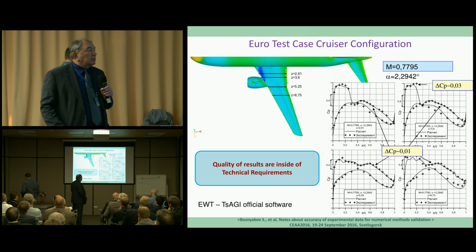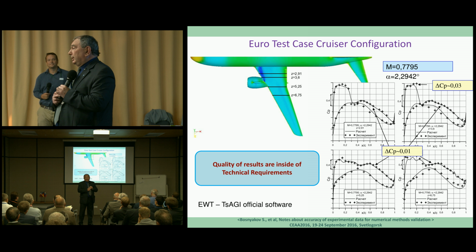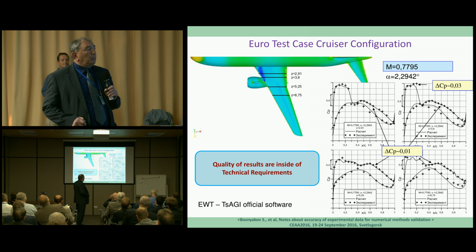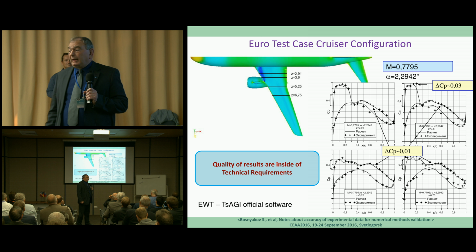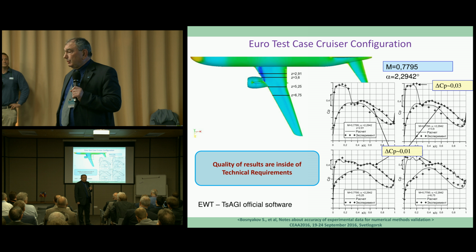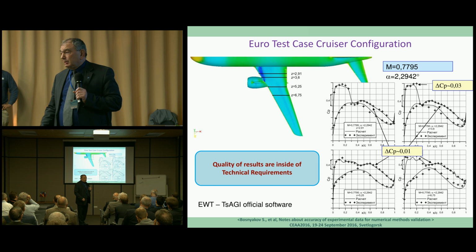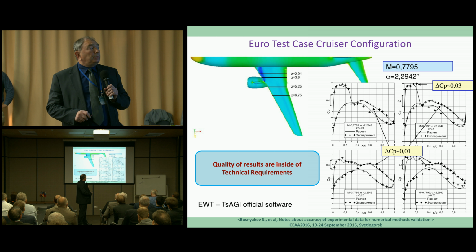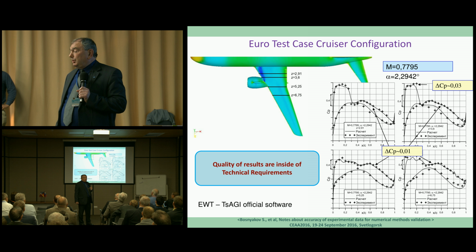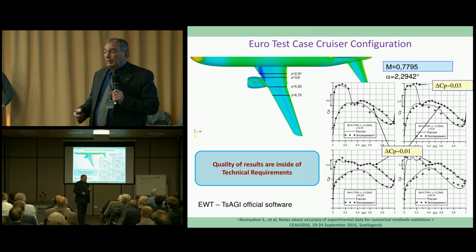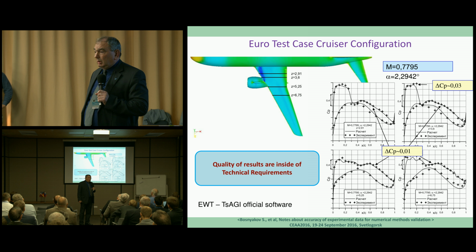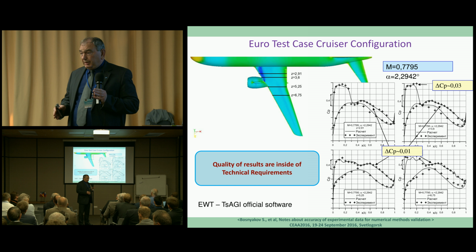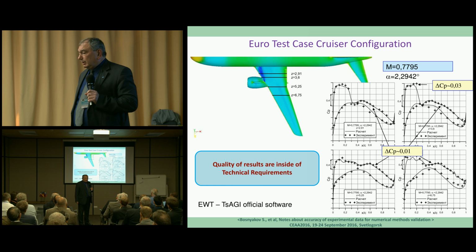So, here's an example of the technical work when we calibrated the TsAGI official code for industrial implementation. And you can see that only one point was out of range. And in this case, there are two ways possible. The first one is to agree with the customer from industry on this deviation, or to adjust or tune. Usually it's possible to organize local tuning for the grid or for the local tuning of the turbulent model. Of course, it's only the calibration stage. When you start to work to optimize geometry or to create any industrial calculation in the frame of the calibration, any tuning is strictly forbidden.